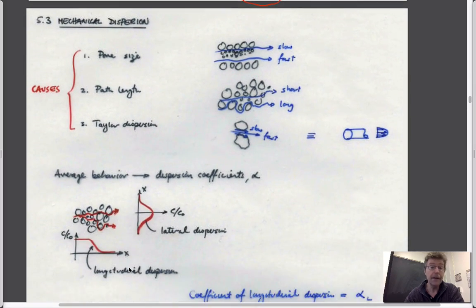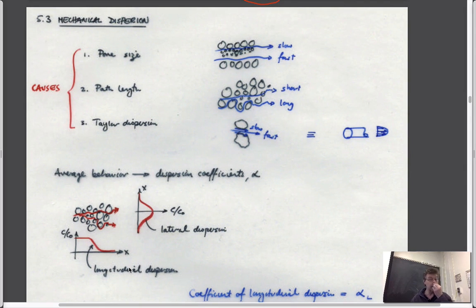So there are a number of mechanisms by which you could imagine this could occur. We've explained kind of how it happens before. It could occur by the fact that we have a distribution of particle sizes and therefore pore throat sizes. We know, for instance, that permeability is proportional to diameter squared, right? Diameter of the particles or diameter of the pore spaces.